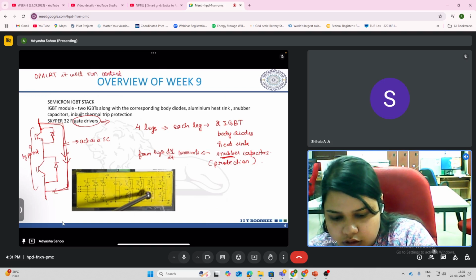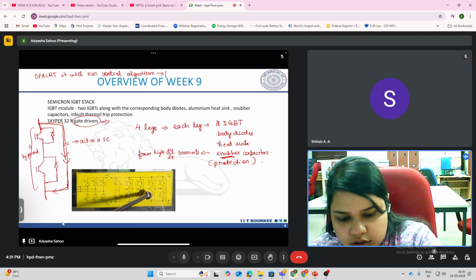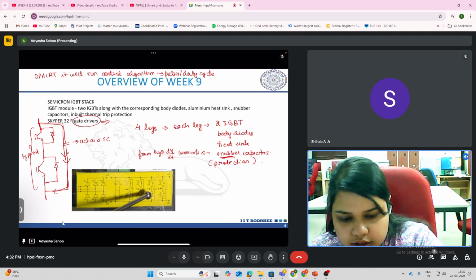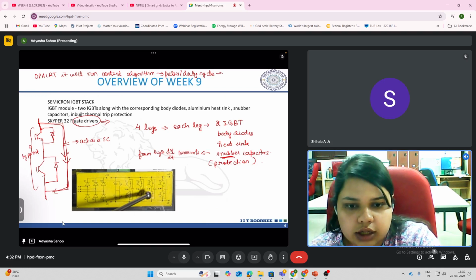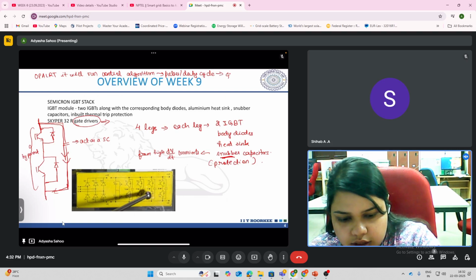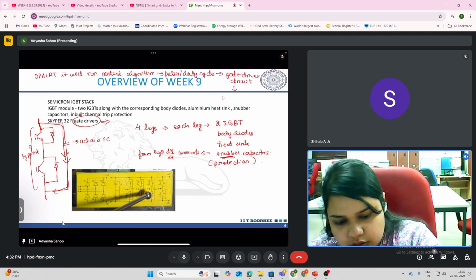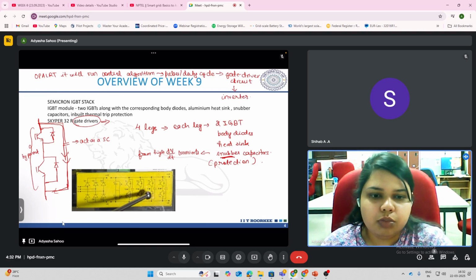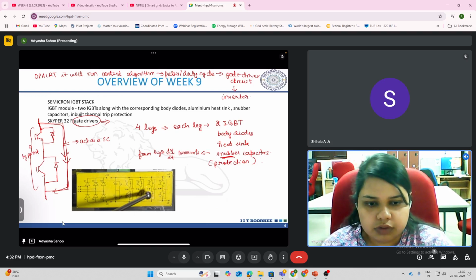After the control algorithm, you get the decision of the pulses or the duty cycle, that is, the desired duty cycle in the current scenario, and this will be given to the inverter through the gate driver circuit. So it is for receiving the duty cycle information as input from the OpenRT platform.